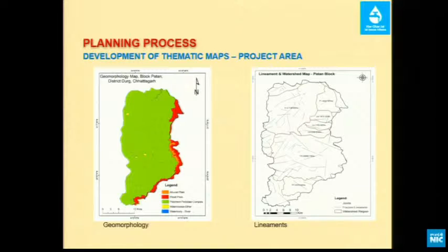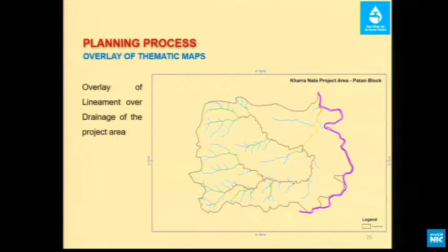We have taken the data from NRSC. Because it is at 10 meter resolution, again we have brought it back here. You see here that these are the lineaments, fault and fissure, which I am showing to you. So lineaments are the most important points where recharging can take place. If I put a structure on that lineament or fault or fissure or geology, this is going to be an excellent recharge point.